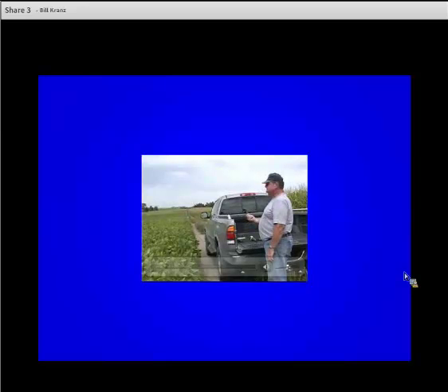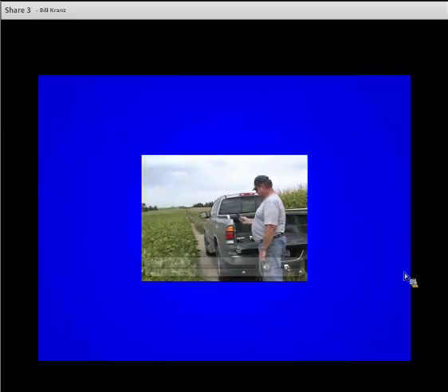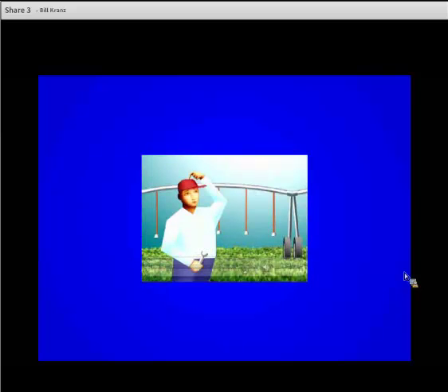And now we're seeing a producer actually go out and replace a sprinkler, basically with something that he just happens to have around, with the idea that he's going to go back and put the right one in there someday. That someday rarely comes when they put the right one back in there. So it's better to have a supply of nozzles to put back there that are the right ones, and at least make sure that the overall distribution is as uniform as we can make it.